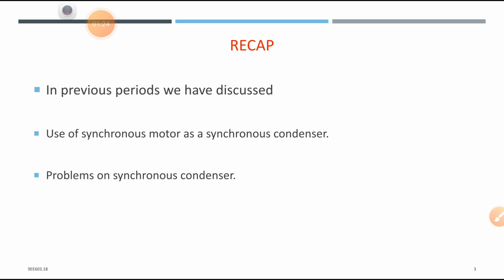When our synchronous motor runs at over excitation, then we are going to generate reactive power which can help to increase our total system, our main industry power factor.